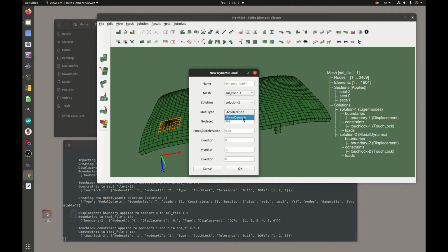Here it's not using the boundary conditions to apply the load. Here you have to set boundary conditions somewhere else and then apply this as a dynamic force being applied to the structure, so that it's being held back with 0 displacement at the boundaries, and wherever you are applying the force is pushing on the structure. But for this tutorial, let's use base acceleration.